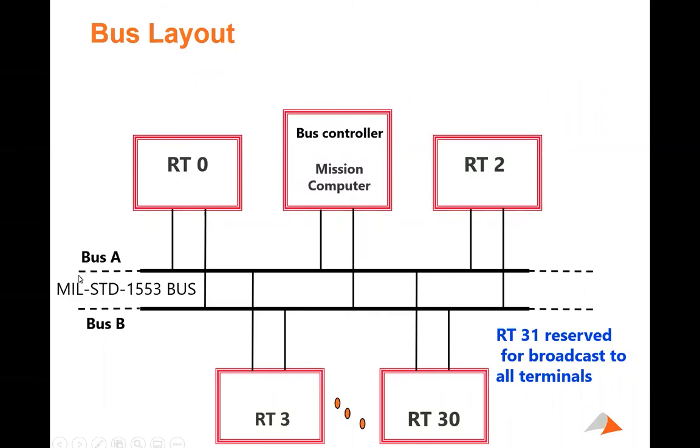One thing we don't have here is that every bus ends in a terminator, a 78 ohm terminator. So basically what you're doing is putting together a transmission line. If you haven't caught on, what we're doing at first is going over the physical aspects of the data bus, and we'll move on from there in just a bit. Any questions regarding this general layout?